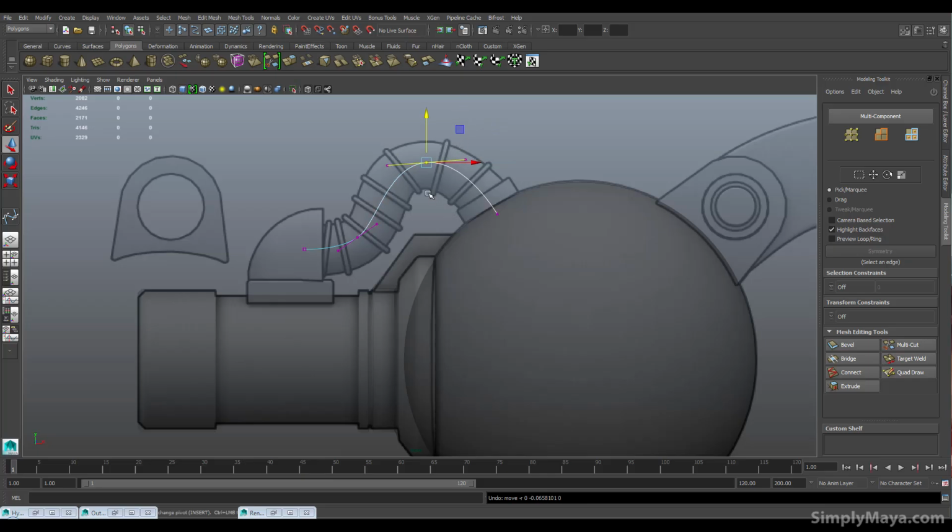So if you just select the curve itself before you select its Control Vertex and just go back up to Create Bezier Curve, this will bring in the original controls for the Bezier curve. So now I can click on this point, grab this one with Control, and I've got all that editing capacity back. So if you are working with one of these curves, you can just get back to it by going back to its Create Bezier Curve, and it will give you all the original curve handles.